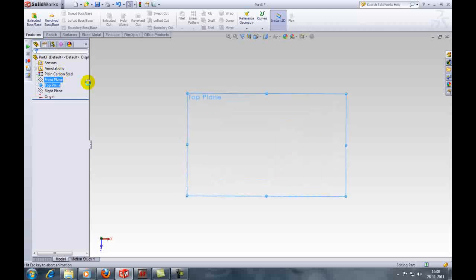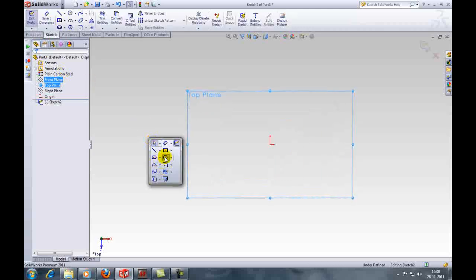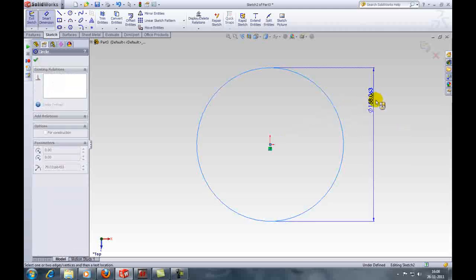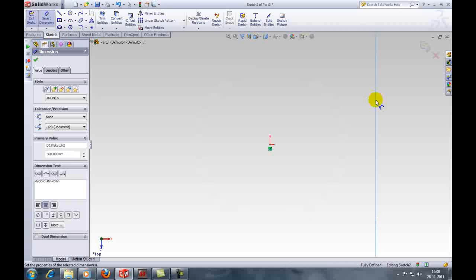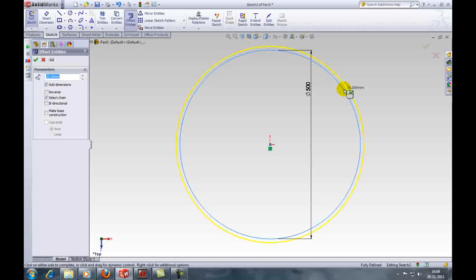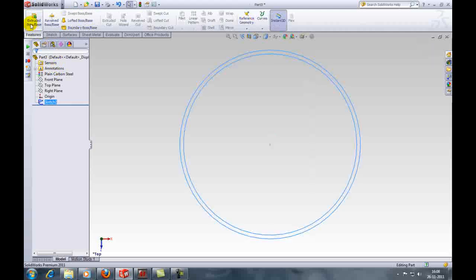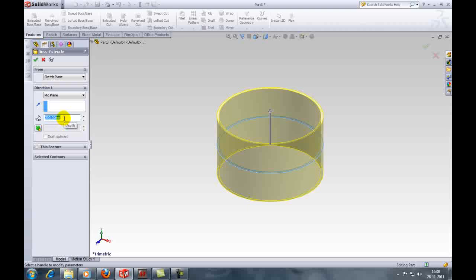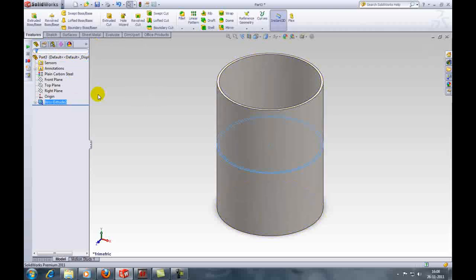For that, let's start a new sketch. Let's give a dimension of around 500. Okay, let's set it by 10 mm, reverse direction, and click OK. Okay, suppose this is my shell of the pressure vessel and I want my length of the pressure vessel to be twice its diameter. So let's say we will just give it a random dimension,